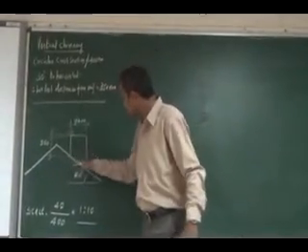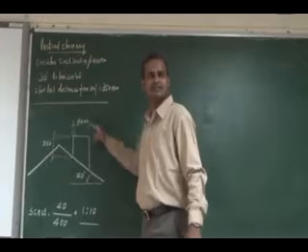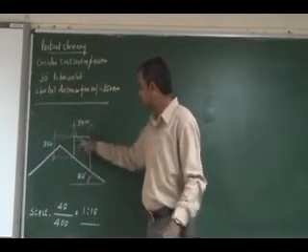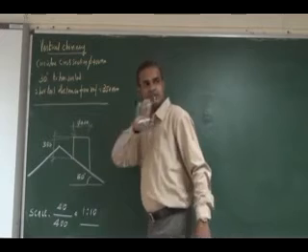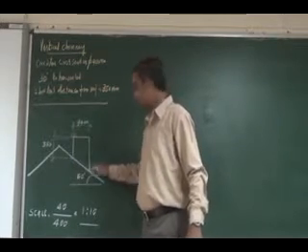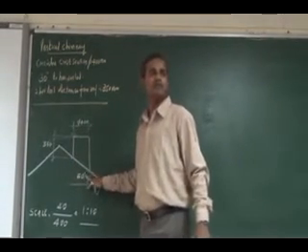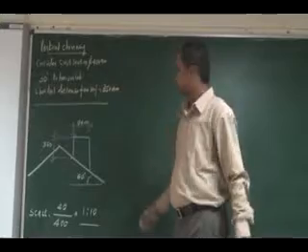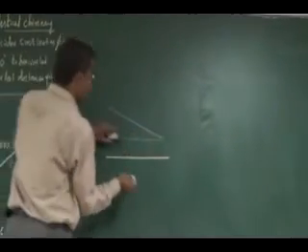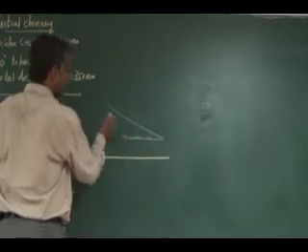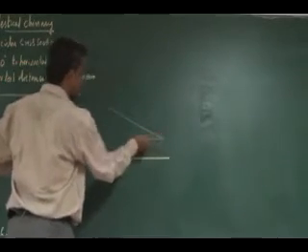Now, this is a cylinder with a cutting plane. Whole thing is something like a cylinder cut by a cutting plane that is perpendicular to VP, 30 degree inclined to the horizontal. So you draw a cylinder and a 30 degree line, something like a slope.